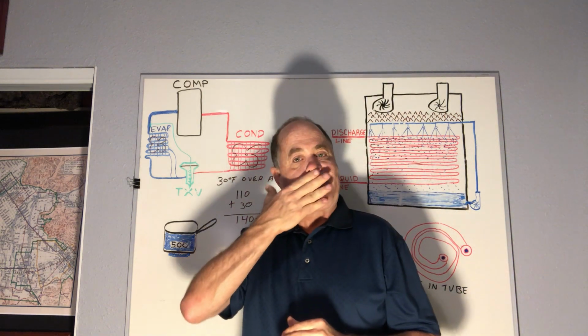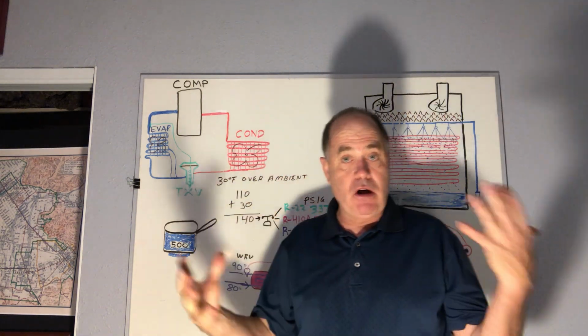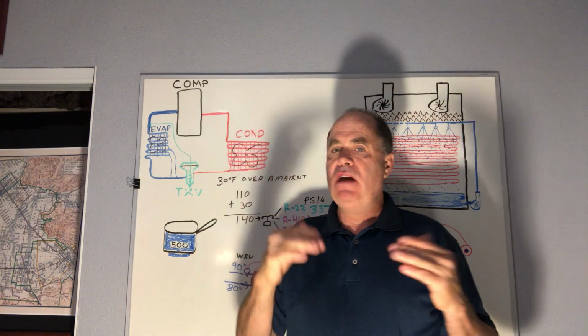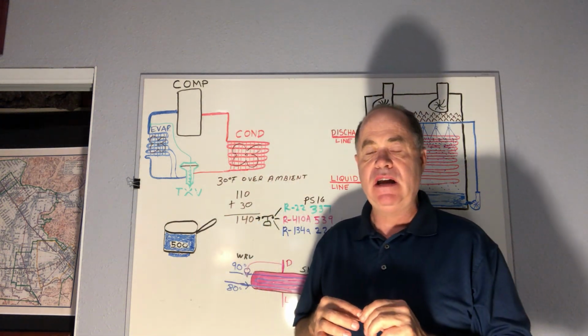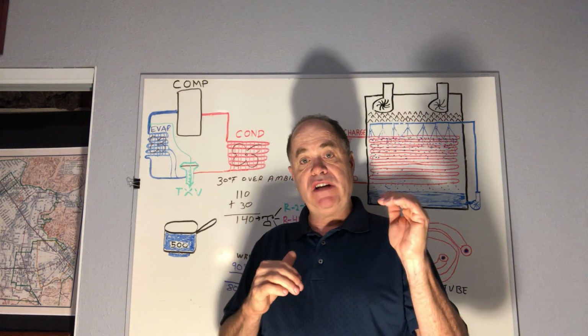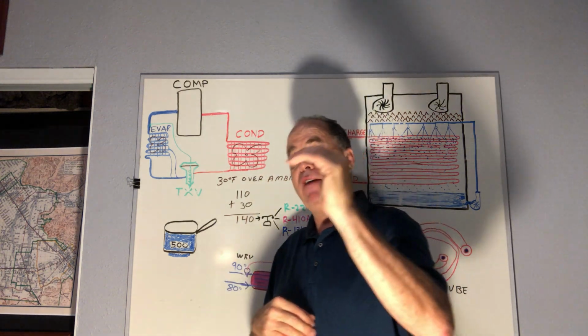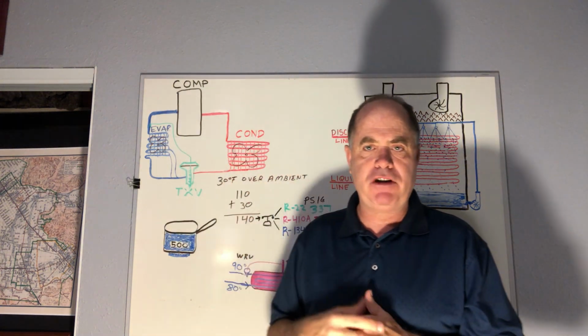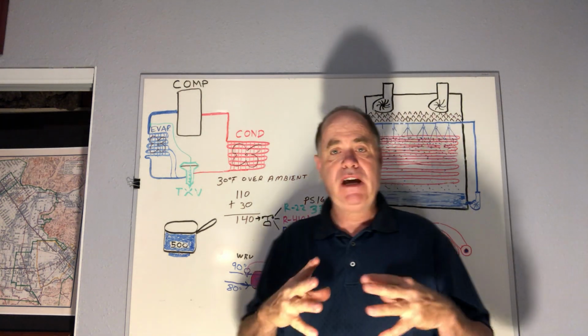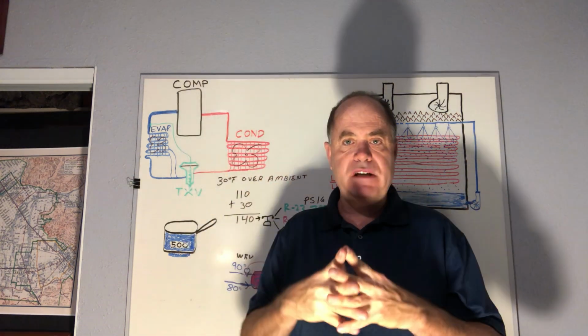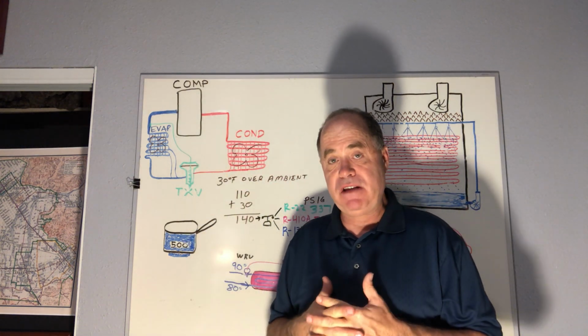Now, with modern systems like R410A, a lot of times the head pressure actually runs more like 15 or 20 degrees above the outside air temperature, where you would take the 70 and look at 85 or 90, and that's actually what your head pressure should be at. But we should never have a head pressure greater than 30 degrees above the ambient temperature.